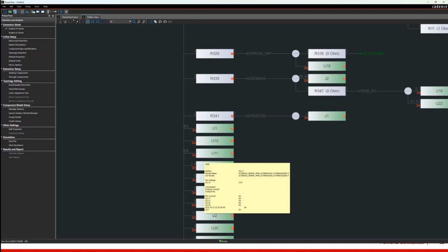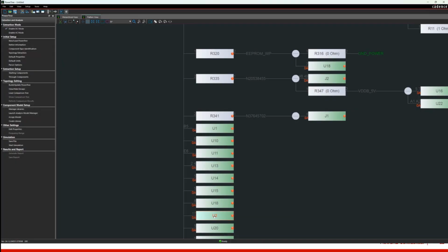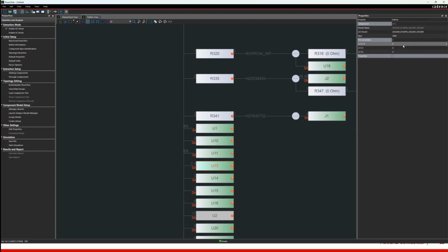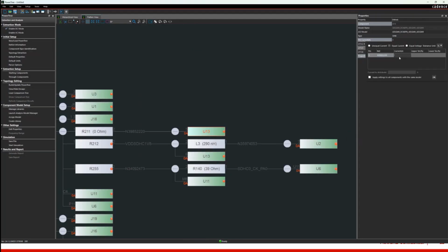Here we have this connector U2 pin number 17, that is the input feedback line, and we say, okay, we want this as a sink, we disable it. It's also a way how we can define such properties. And finally, we can double click here on the items, and then we can say, okay, this candidate has a current, let's say 1 ampere for all 5 pins, that is distributed in an equal way.